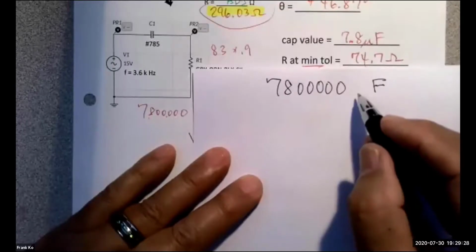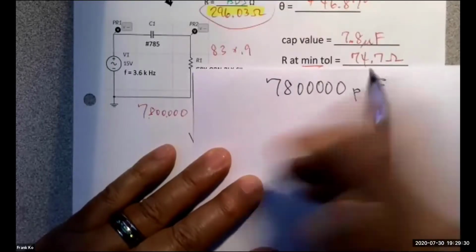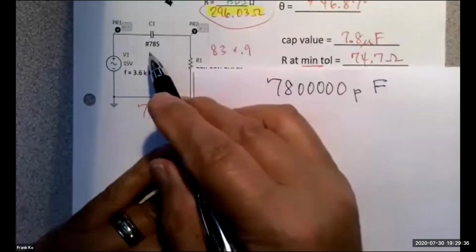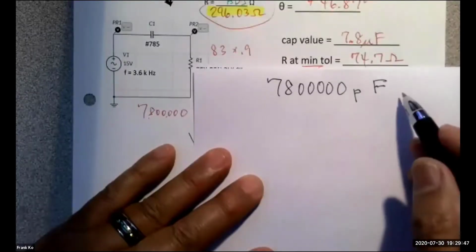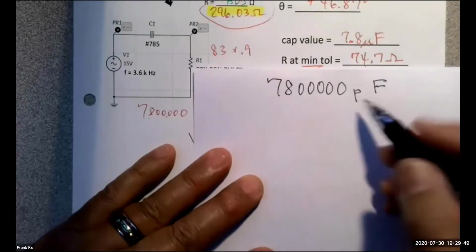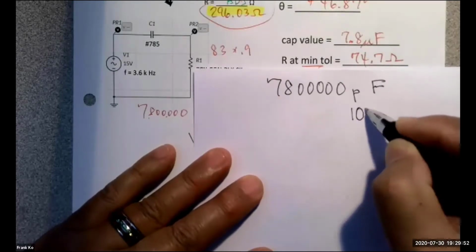Right. Do you remember? It should be in your notebook because you can use your notebook. It's right here. Picofarads. Okay, yes. Got it. That's the P. Yeah, anytime we're decoding 3-digit codes for a capacitor, it's always picofarads. Make sure it's super visible in your notebook. And what you've got to remember is when you key this in, 7, 8 with these zeros, what power of 10 is a pico? Again, that table should be in your journal as well. Pico is -12, right?